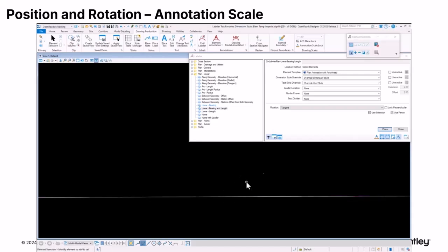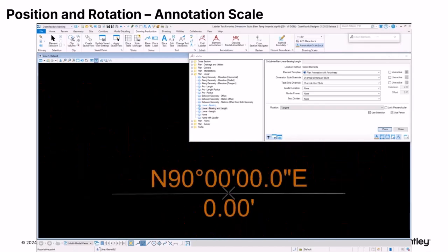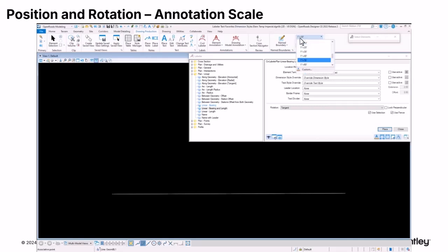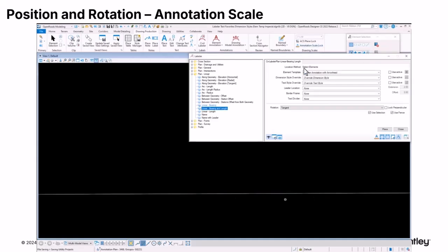It's not recognizing any scale or factor, compared to when it's toggled on. Then the annotation text becomes aware, and gets scaled up relative to the active drawing scale, I should say. We're just demoing various scales here, not really placing anything. So I think 1 to 10 next. You can see how the overall size of the text in the annotation scale interacts.